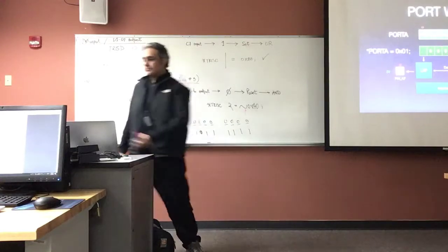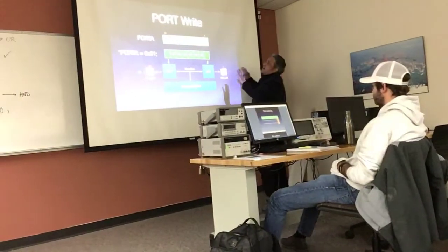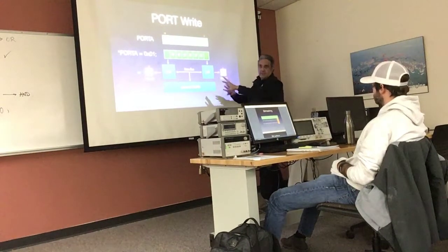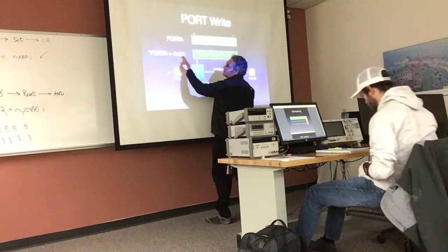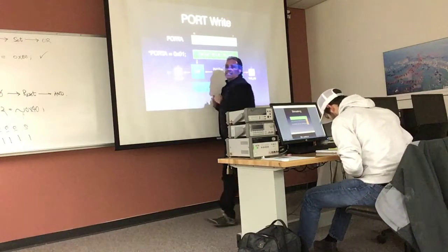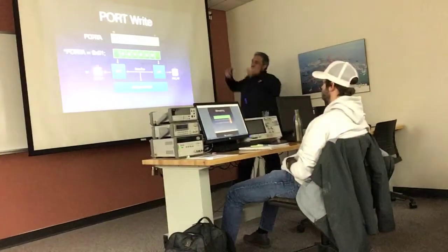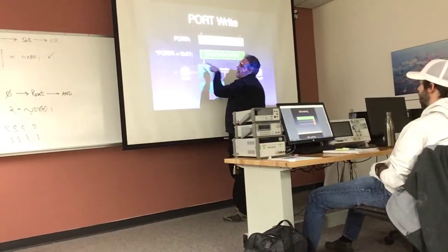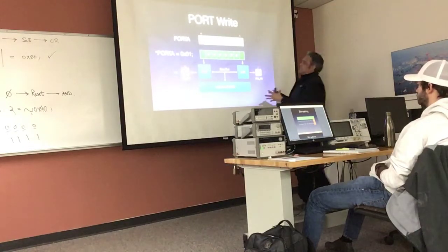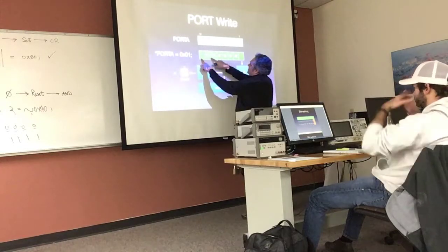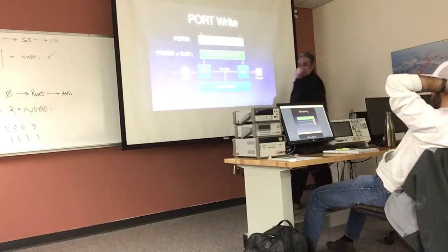So let's take a look at the write operation. Okay, once again, if I am going to be doing a port write, the behavior begins with software. So you start looking at this from this position. You initiate the write. So in software, I write this number into that register. What that does is that it puts the number 0000, that's the first 0, and then the last 4, 0001. Okay?